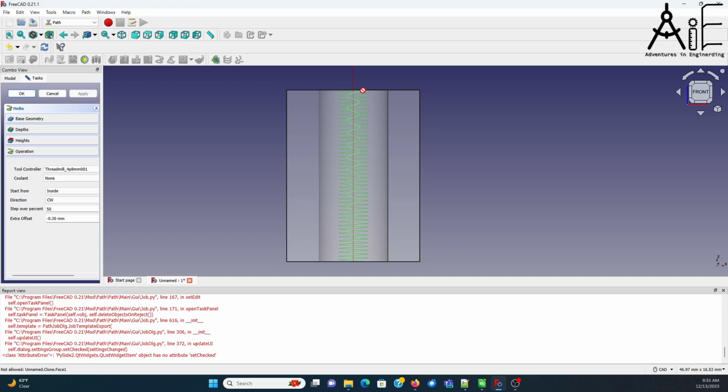Note that it starts on the right side of this, what looks like a sinusoidal wave, but it's really a spiral. So now we can count. We can say 1, 2, 3, 4, 5, 6, 7, 8, 9, 10, 11, 12, 13, 14. Well, I know that the part was 13.5 millimeters thick, and it made exactly 14 spirals into the part. So that is not 1.0 millimeter pitch.